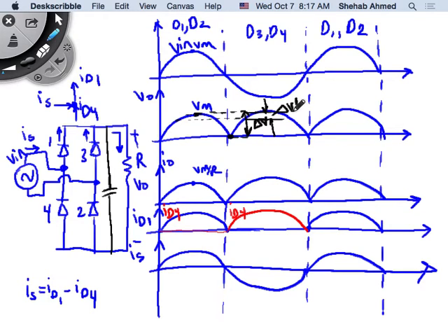So this delta V prime. I want a delta V prime that is only 5% less than my peak value. So it's half a volt less for the case of 10 volts, for example, or it's equal to 0.95 of the peak volt. So if you go from Vmax, you write 0.95 Vmax, and you go down a little by 5%, and it means that you have a capacitor that is allowing your output voltage to look like this, right? Is everybody okay with that?